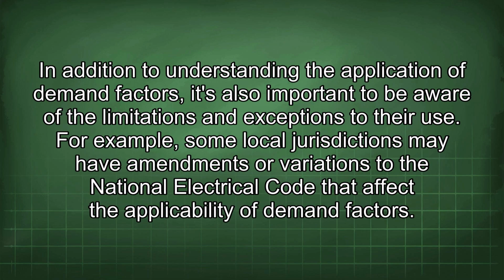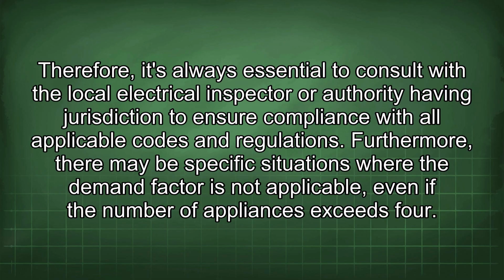In addition to understanding the application of demand factors, it's also important to be aware of the limitations and exceptions to their use. For example, some local jurisdictions may have amendments or variations to the National Electrical Code that affect the applicability of demand factors. Therefore, it's always essential to consult with the local electrical inspector or authority having jurisdiction to ensure compliance with all